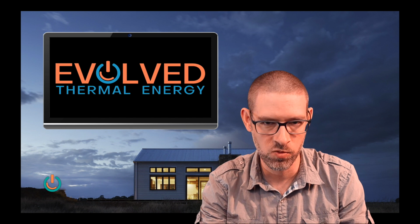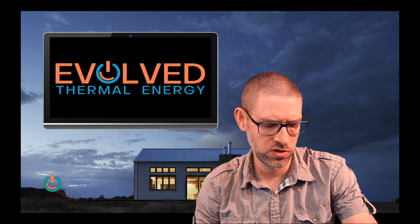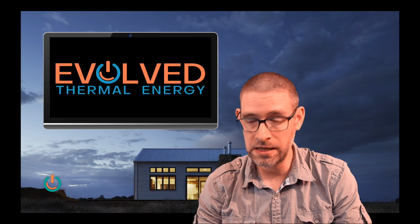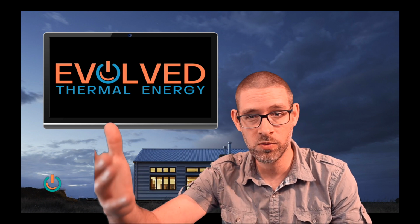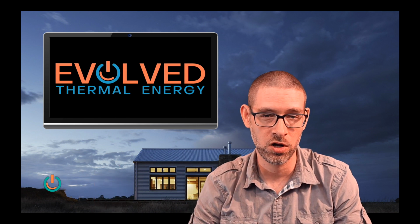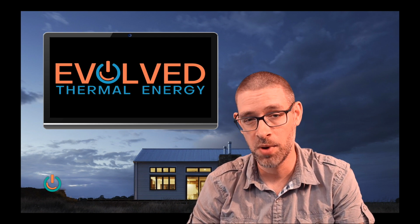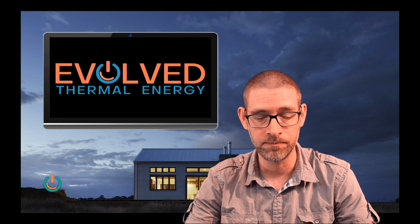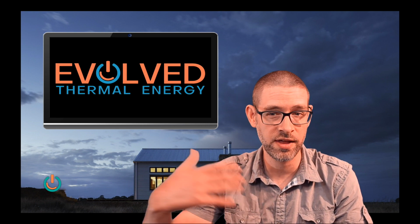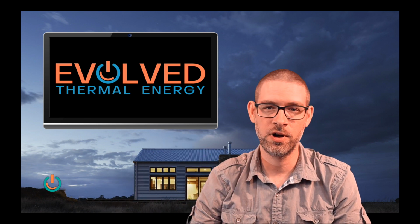That's the amount of energy that we're delivering into the home. And let's say we're at 65 cents a liter of propane, which I don't think is out of the realm. We'd be about $3,325 a year just for heating. And then we'd add cooling to that, because my original figure had cooling. Depending on what type of air conditioner I have, I could be a few hundred dollars a year just for cooling. So quickly we get to a savings of about $2,000 a year compared to propane. Oil would be probably fairly similar, $2,000 or a little bit more. So you can see how that $2,000 a year can start to add up quickly to the cost of a geothermal system.